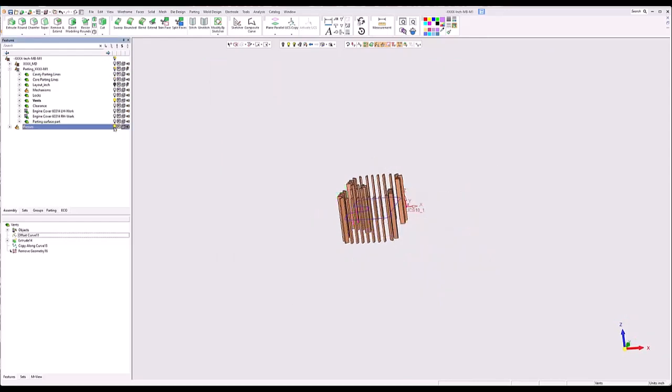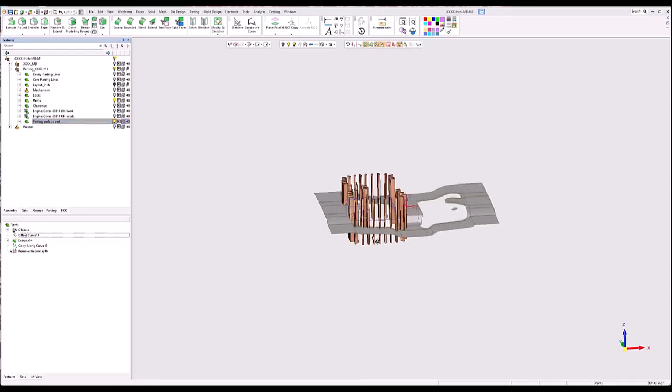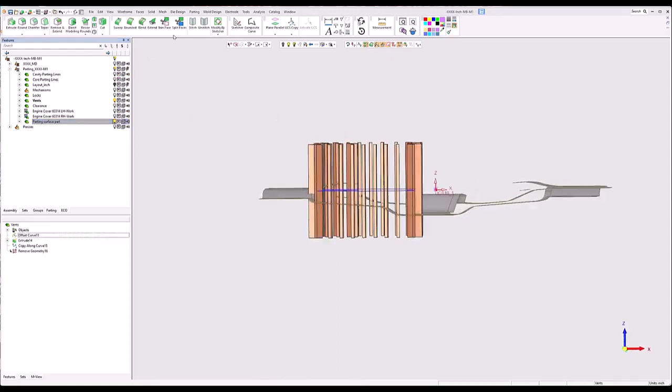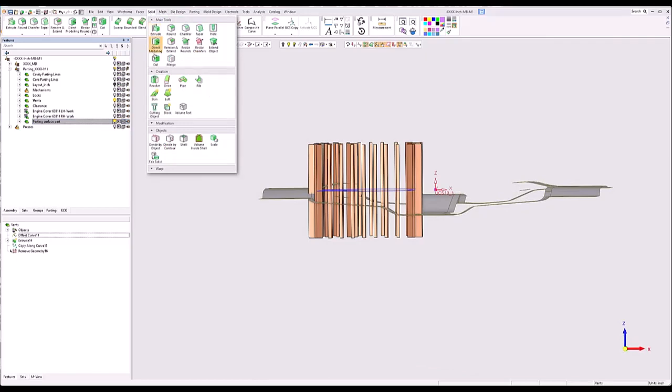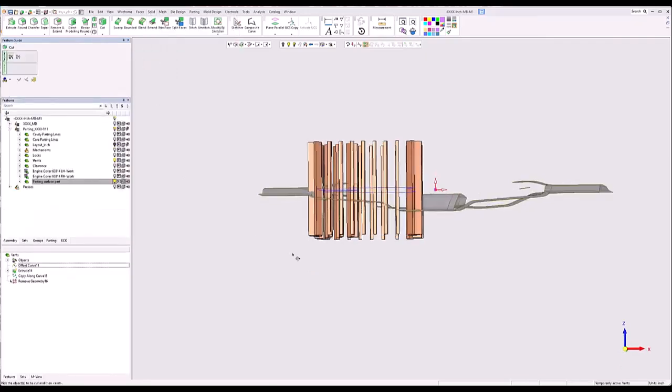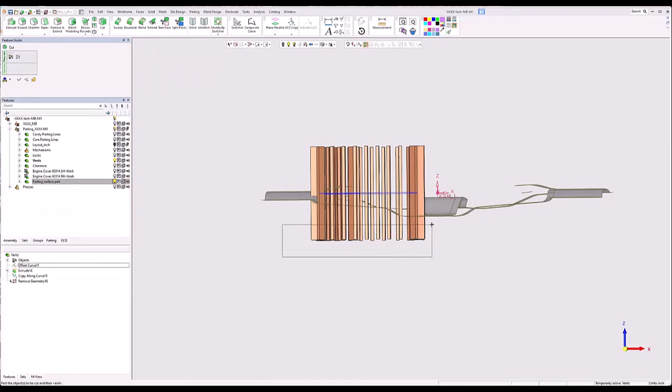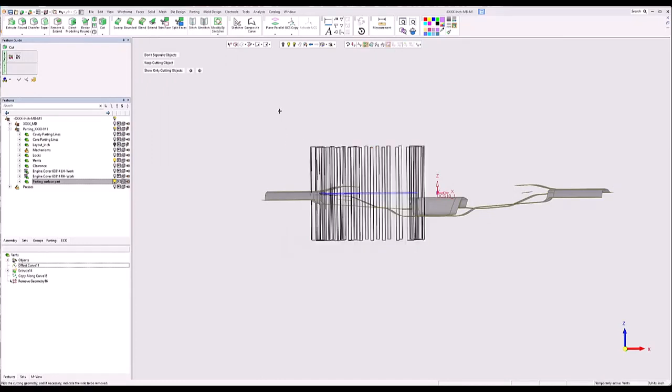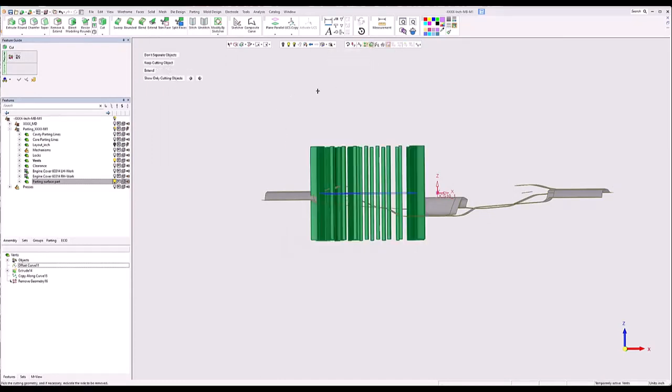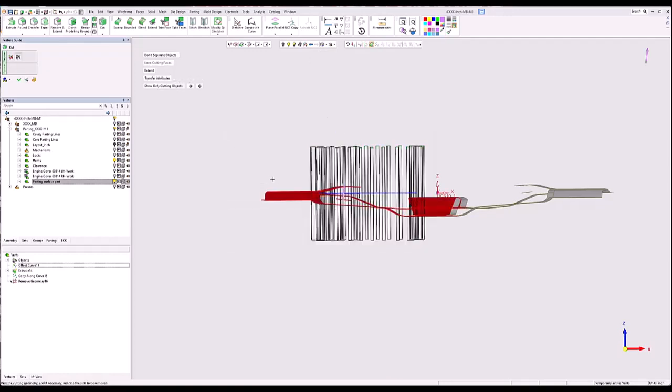I am going to use the parting surface part to cut these and go solid cut. Turn off extend. It failed with extend on. A lot of times this will have it work successful.